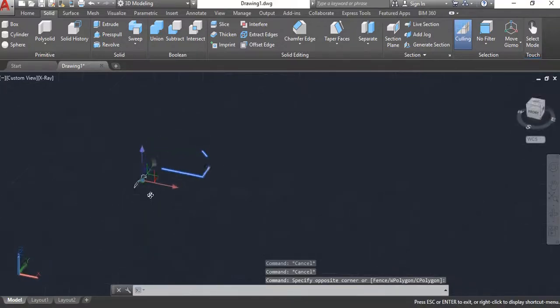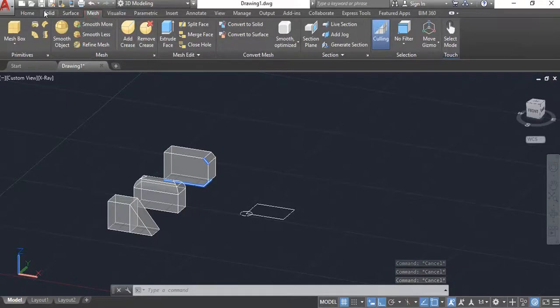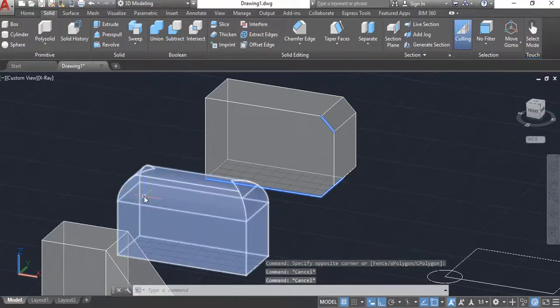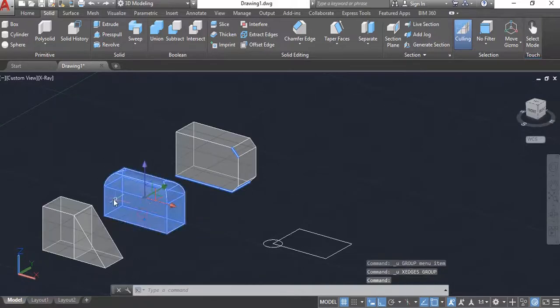In old school AutoCAD, we used to call that wireframe modeling. I think they might still use that term some. Mesh modeling. So watch out that you don't leave those lines in there. It will mess you up later on as you go to snap to edges or you start moving things around. Sometimes it'll give you errors.